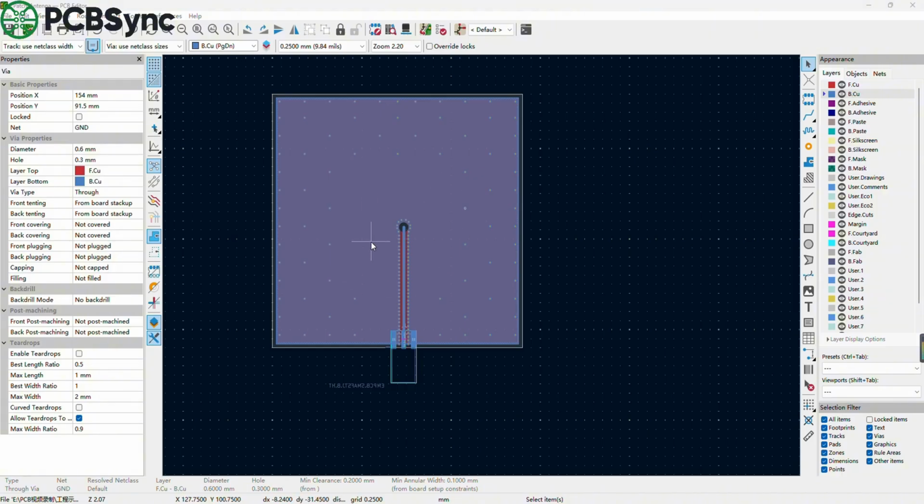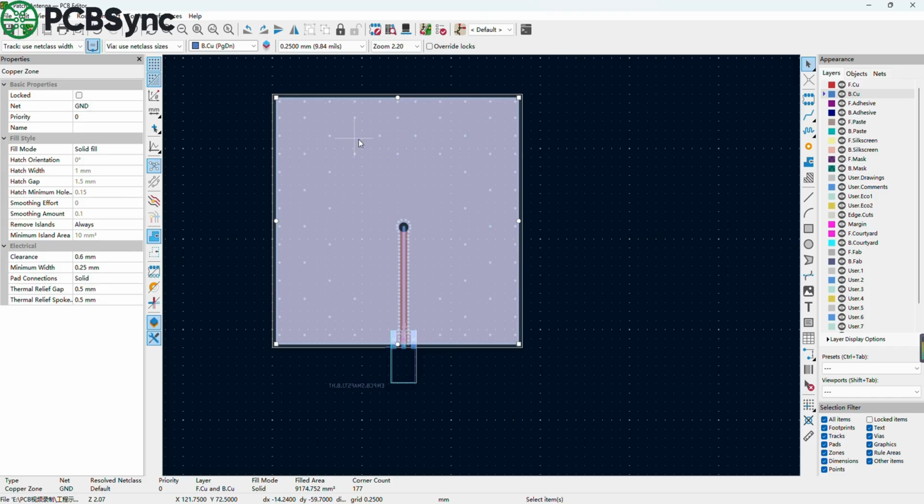Suppose this antenna was originally designed using standard FR4, and now you want to switch to RO4003. You can't just swap out the material name and keep all the dimensions the same. First, we need to recalculate the size of the radiating element, the effective wavelength of the antenna, and the material DK. After the DK changes, the required patch length and width to achieve the same operating frequency may also change.